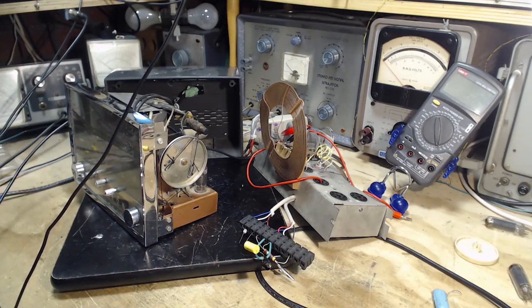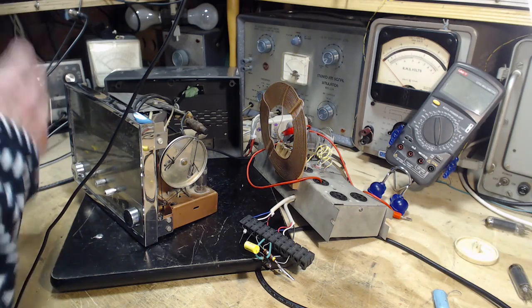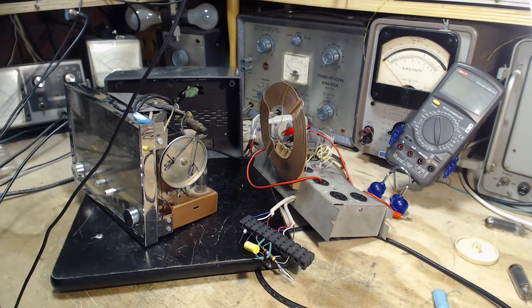I'm going to stop for a little bit, take a little break. I think I'm going to apply a signal generator to this and listen to that. Do a little signal tracing, see if I can find a spot where things go downhill, where the sound quality goes down, and there's just not a lot left in this radio to change. Really, I should just go change the last two capacitors, but I don't like shooting in the dark like that.